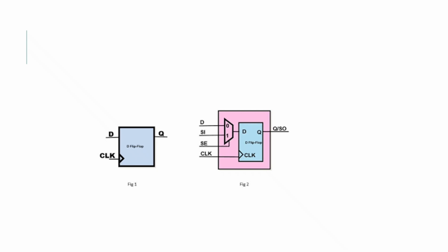We need to gain more scan coverage. We need to review the scan reports and make sure that the scan insertion is clean for us.